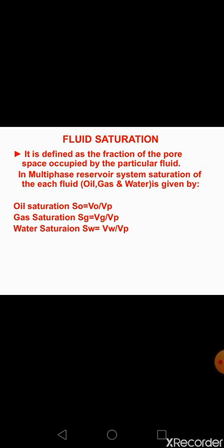So next property is fluid saturation. It is defined as the fraction of the pore space occupied by the particular fluid. In a multiphase reservoir system, the saturation of each fluid like oil, gas and water is given by the following equations. For oil saturation, it is given by volume of oil divided by volume of pores, that is Vo